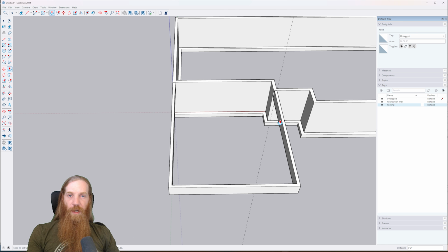12 inches gives you plenty above grade for your garage, both on the outside, but also on the inside. You have a nice high concrete lip along all the walls, so that if you choose to wash out your garage with the hose or something, and you have drywall on the walls, you're not too concerned about splashing water up onto the drywall. It won't be a full 12 inches because you're going to have your slab there as well. No, sorry, the slab will be set 12 inches down. Typically, I mean, you can set it where you want to.